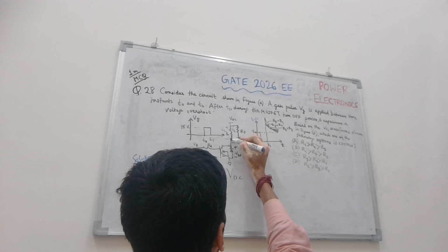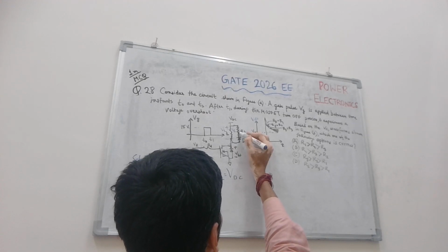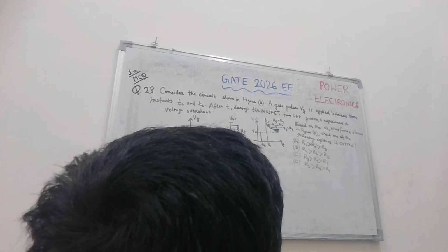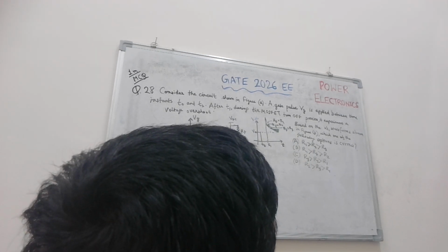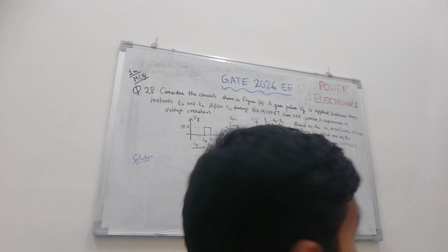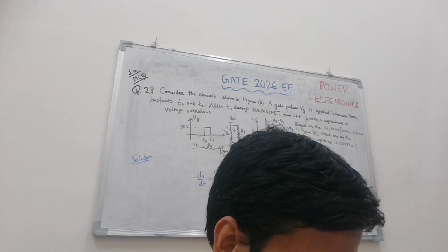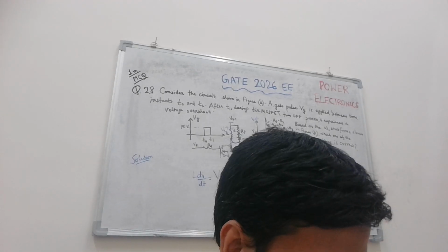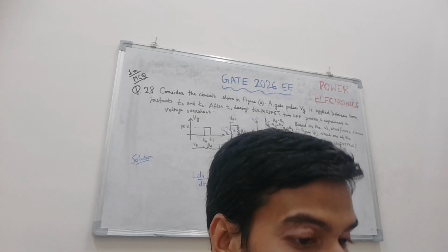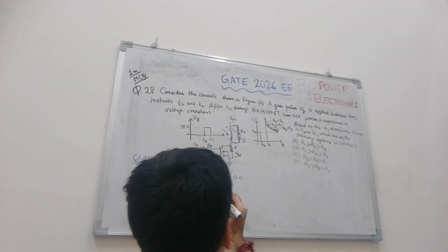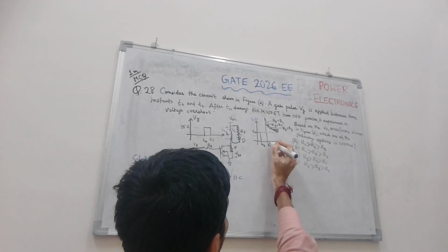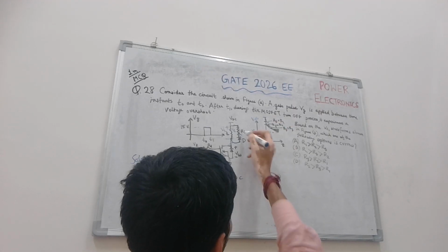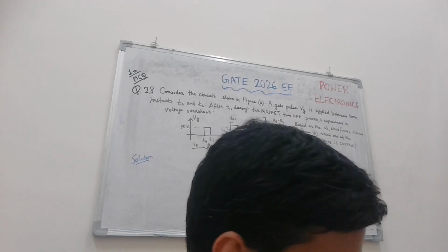Open switch means this inductor current will have no other path, so it will circulate in this loop through the resistor RF and the diode D, discharging the inductor L. So the initial voltage spike in VDS at T1 is a function of this RF actually.